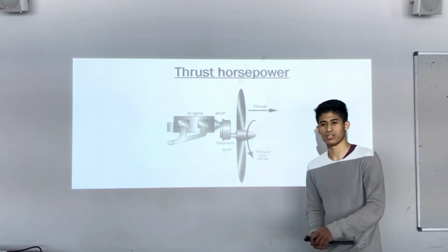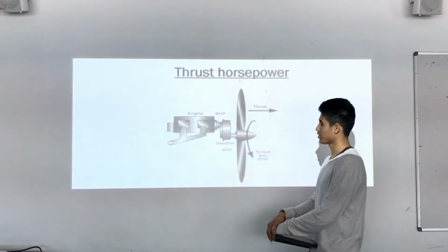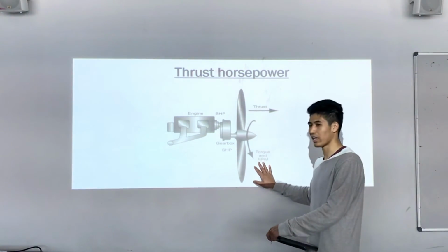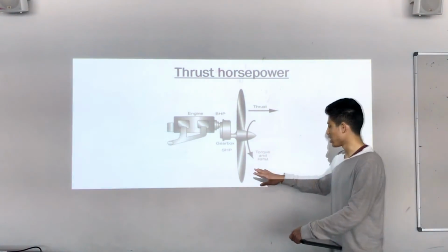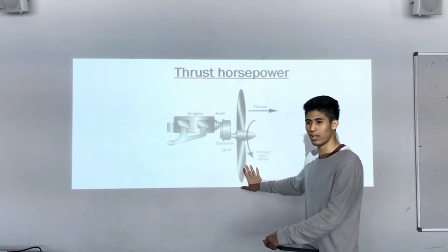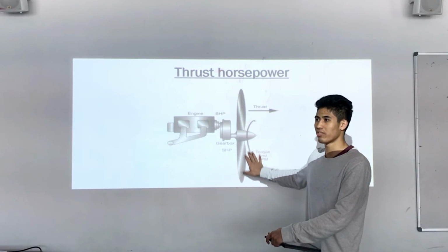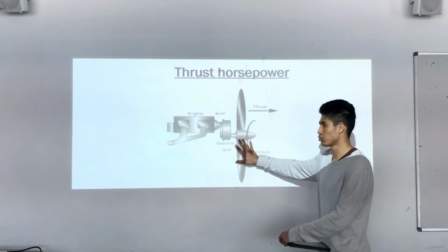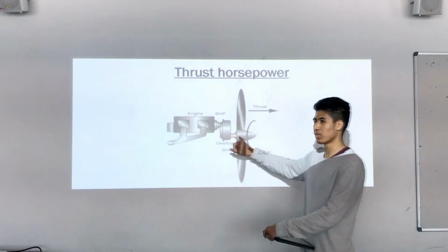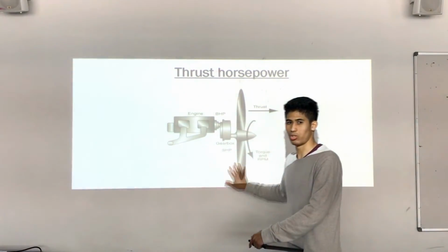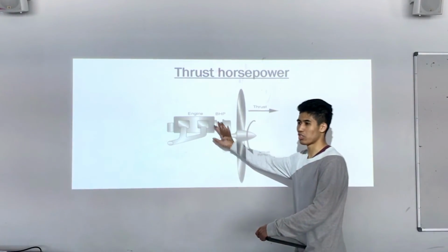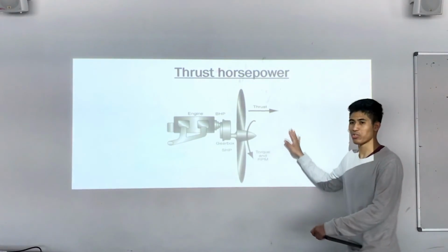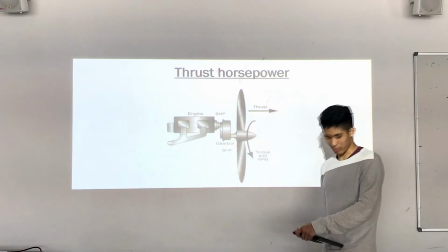100% efficient. One of the reasons that we lose energy in the process of turning the propeller is that the propeller, since it's exactly like a wing, has aerodynamic forces, and with a fixed pitch propeller like in a Cessna 172, we won't always have the most efficient lift to drag. Furthermore, energy can be lost due to drag, and the friction between the crankshaft and the propeller and the gears driven means there is a further loss in energy. After all the energy lost due to the aerodynamic forces and the friction in the engine, the energy that's left to actually produce thrust is called thrust horsepower.